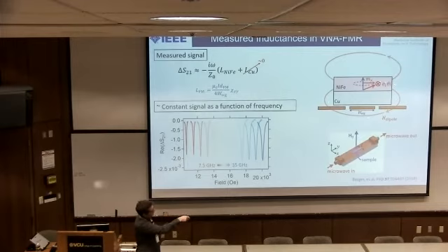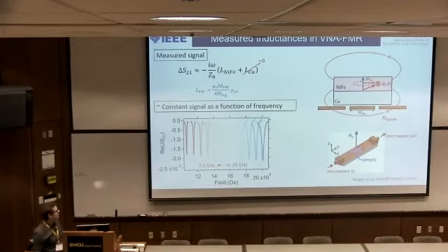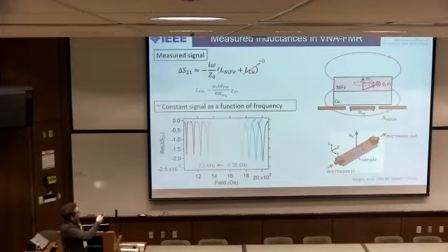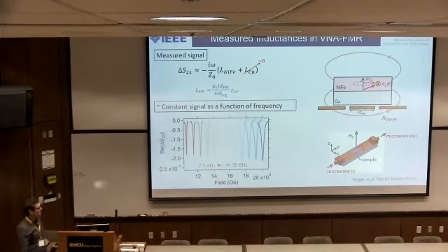And what you see is you get this magnetic flux that winds around the center conductor shown there. We pick that up with the VNA. That's our signal. When we measure FMR, that's the signal that we measure. We'll also get Faraday-generated currents in this copper, but we can ignore them for now. And so the signal we measure here is simply proportional to the inductive coupling between the permalloy and the waveguide, given by this parameter right here. That predicts that the response that we measure is frequency independent, both the phase and the amplitude. And we can see that in the raw data. We measure it from 7.5 to 35 gigahertz, and we can see the phase and the amplitude are relatively constant in this particular case.